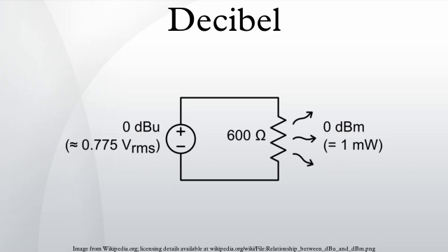The ratio of 1 megawatt to 10 W in decibels is obtained with the formula. The power ratio corresponding to a 3 decibel change in level is given by the following. A change in power ratio by a factor of 10 is a change of 10 decibels. A change in power ratio by a factor of 2 is approximately a change of 3 decibels.